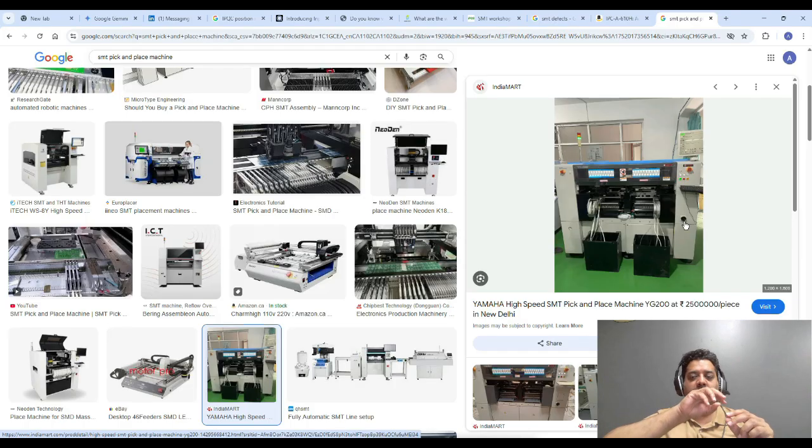What you want to do is place 1, 2, 3, 4, 5, 6, 7, 8, 9, 10, 11, 12, 13, 14, 15, 16. So you go in this path where you're spending the least amount of time pick and placing, because that's how you optimize your program. That's how you optimize efficiency. If your machine is going all over the place, then it's taking more time for placement of the components. So that's where the optimization comes in.